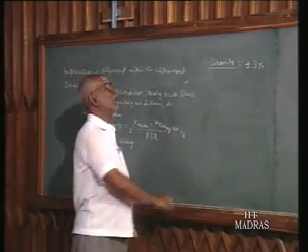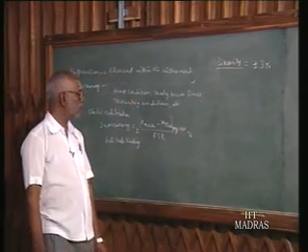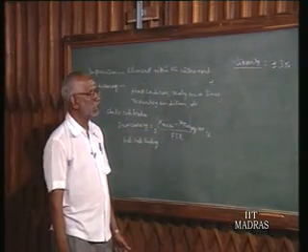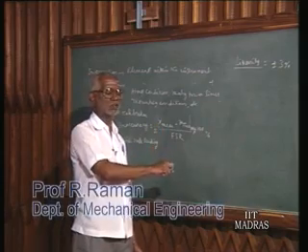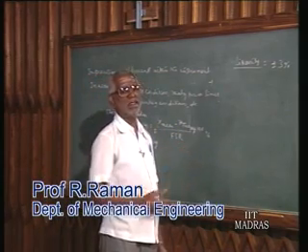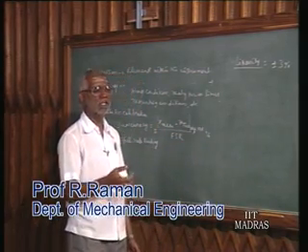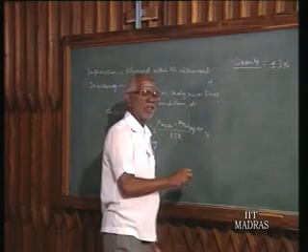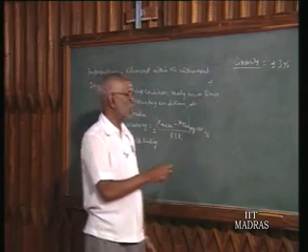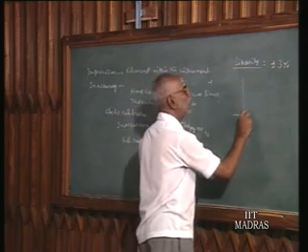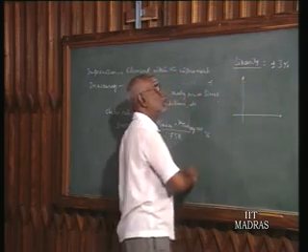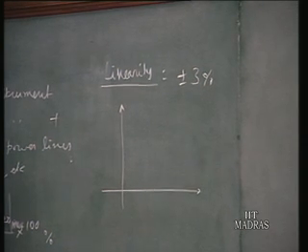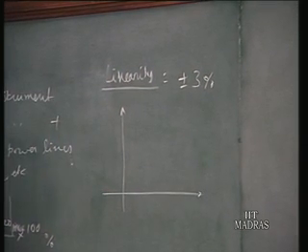So to understand nonlinearity, we have to do a different type of experiment. Probably you can assume the same setup where pressure is given to two instruments, one is the standard instrument, where we read the actual value. The other one is the instrument under study. Such a setup, but instead of keeping the input signal the same as 50 bar, here what we are going to do, we will change the input signal or pressure from 0 onwards. This is the little change in the experiment to understand the phenomenon or concept of linearity.